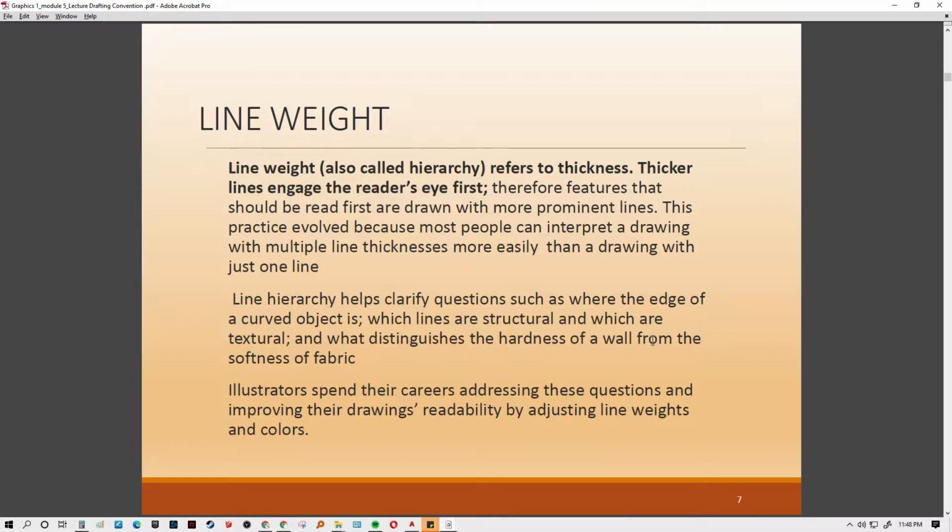Then the secondary details are the openings, or the fenestrations, which are the doors and windows. They're a bit thicker, but not as thick as the walls. Then the last ones are the furniture, the line modules, the guidelines, the fonts or the text and numbers, the dimension lines. So it's like creating a hierarchy of those important details you have to be interpreting in each drawing.